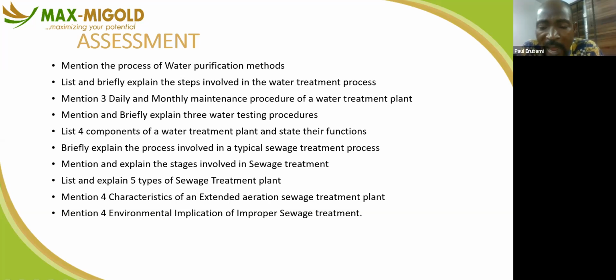So it's two options. You can either increase the height of the tank. That will give you a better gravity. Or you leave the tank on the floor as it is and, since it is just only toilet, get a 0.5 horsepower pumping machine. Put a pressure switch on it and it will use it to send water to the toilet. That will give you a better pressure.